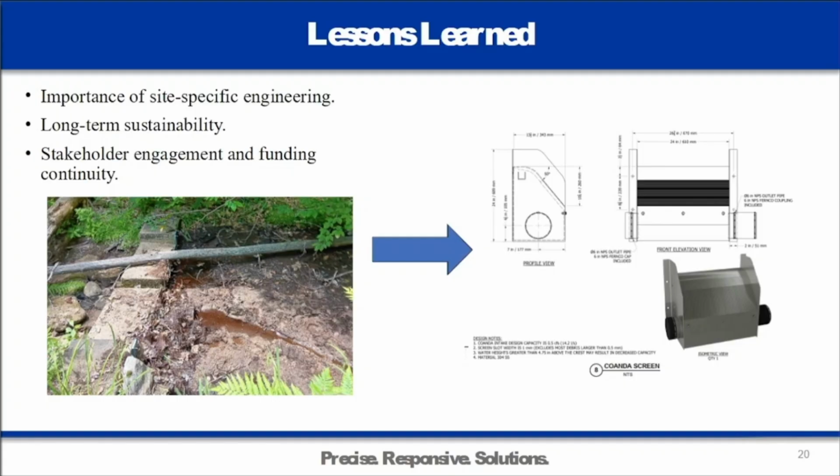So with the next system that we designed, I looked at using a Coanda intake, based on some other people's recommendations, as leaves tend to get into the orifice of the Mosquito Creek systems. And we wanted to pass this gravel. So I designed the intake to have the gravel go over the top and go downstream, passing the bed load at a really high flow event while still allowing me to take water off.